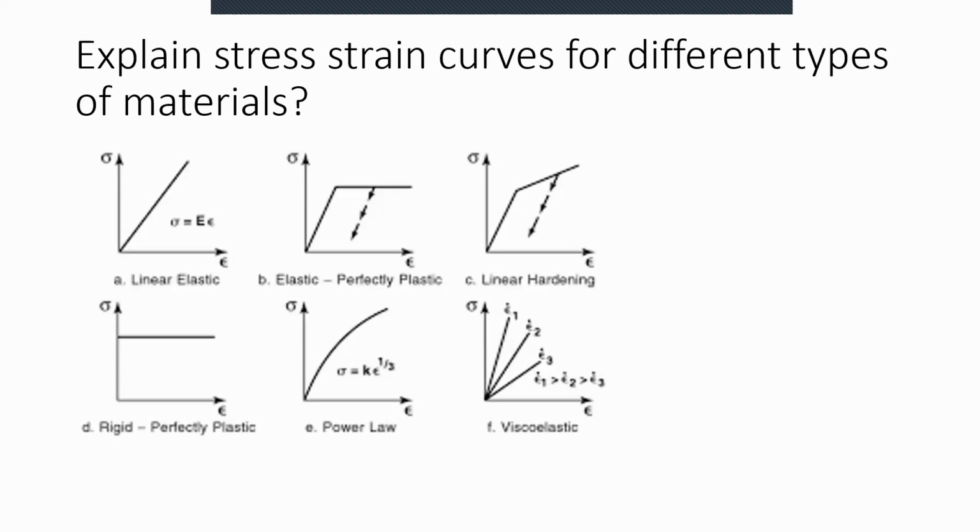These have been used to show you what is meant by elastic recovery. Suppose you have subjected a particular material to a tensile test, or to some tensile loads. The material deforms up to the elastic limit, and then the elastic region is gone and the material becomes plastic. Now you remove all the loads at some point in the plastic region.